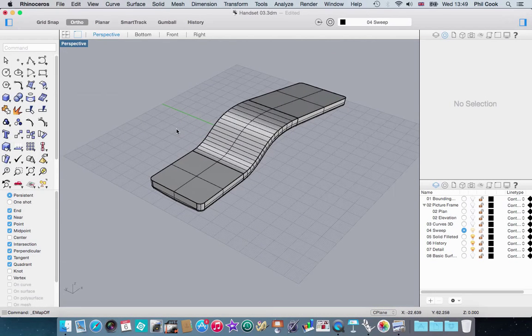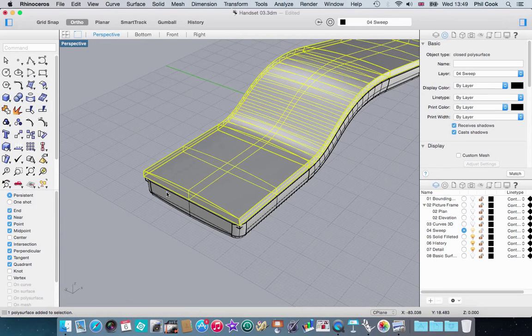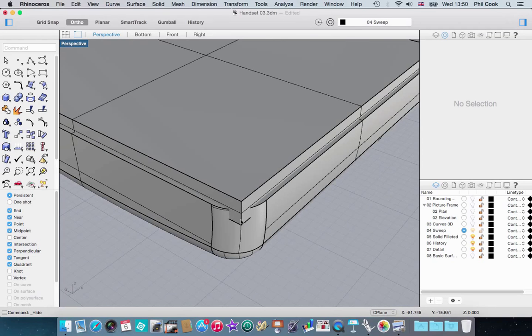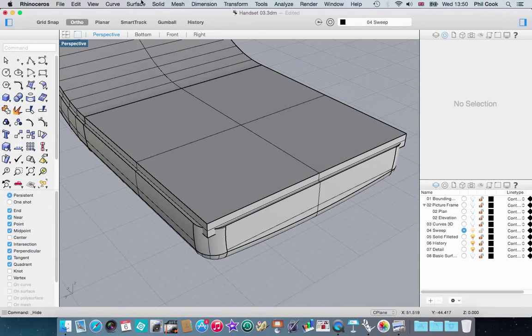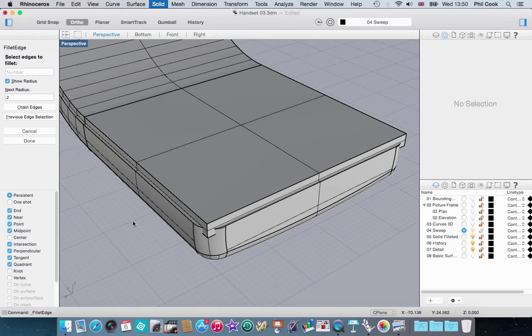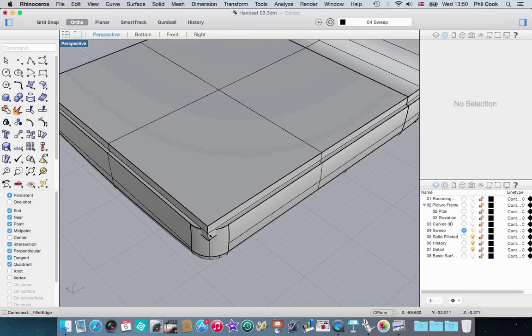So now I'm going to fillet the remaining objects. So I'll show these back in. I'll just hide the top for the moment. And let's fillet these corners here. So here I want to set a radius of 3 millimeters. Because I've got a 0.4 step here that I'm trying to create, I'll do this on these corners.